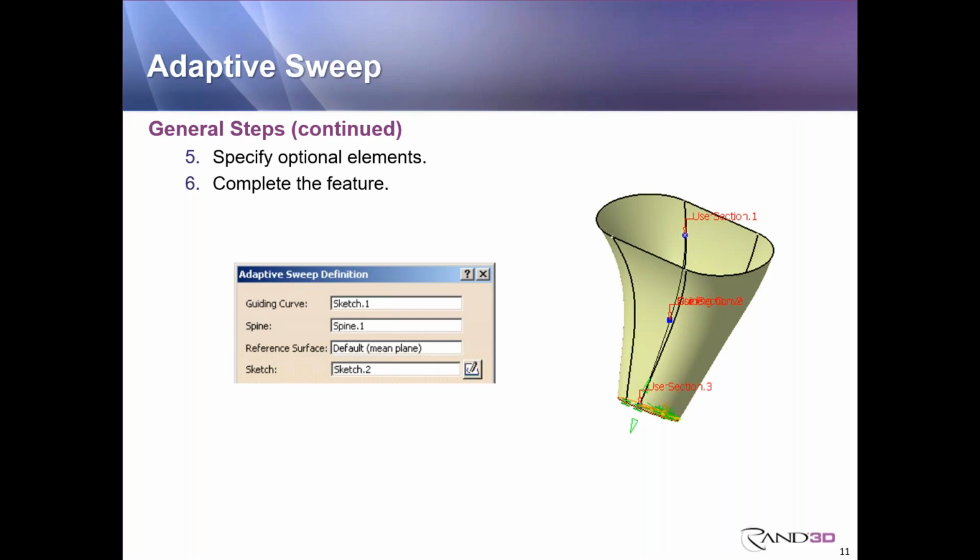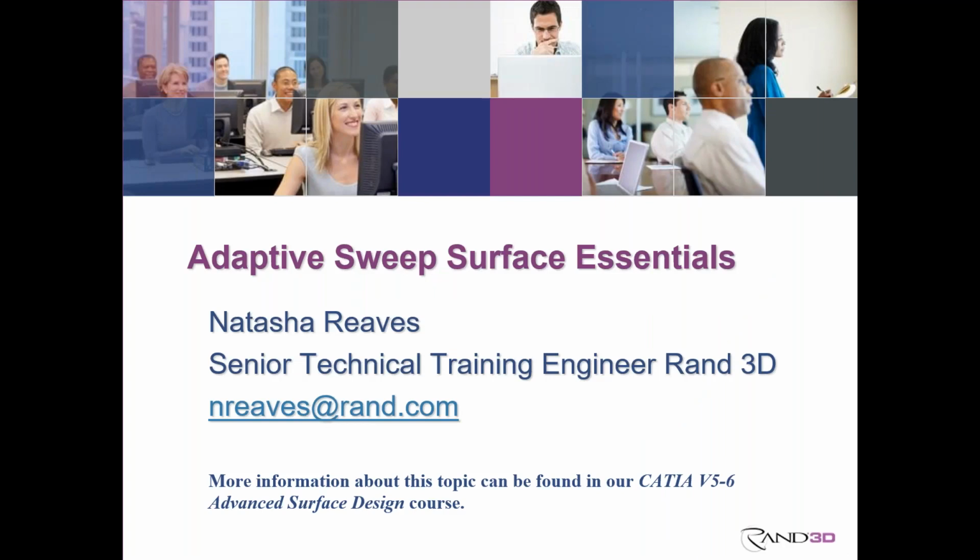And so that's everything that I had information-wise for the sweep surface, the adaptive sweep surface. You do have the information that I added in there about the explicit sweep from that standpoint. The adaptive sweep is in some cases more flexible because of that capability of generating the different shapes based on selected and specified points and then edited constraints along those points.